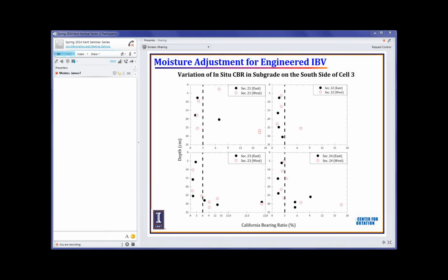And the bottom values, I will not worry about those, because if you think about the pads of the sheep's foot, it itself is 2 to 3 inches high. So if you are doing your DCP at the bottom of that depression zone, that counts for the 2 to 3 inches. So that's why you have ended up with pretty high CBR values at the bottom.